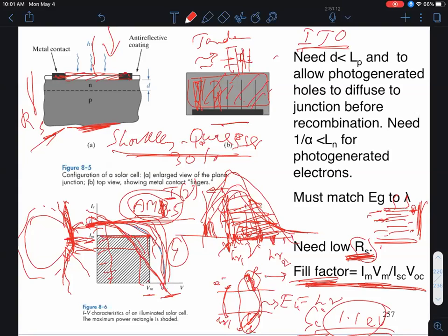So you have to add up all the energy required to grow the crystals, make the solar cells, et cetera, okay? So if you add up all the manufacturing energy input, you have to match that with how much energy you can get out of the solar cell, right? So that is governed by what's called kilowatt hours. So the kilowatts that you can generate from a solar cell array times the number of hours it operates for, okay? So kilowatt has units of power, and times the operating time in hours gives you units of energy. So you have to determine how many kilowatt hours of energy you can get out of a solar cell, right? So that, of course, will depend on the number of hours of sunlight times the lifetime of the solar cell, right?